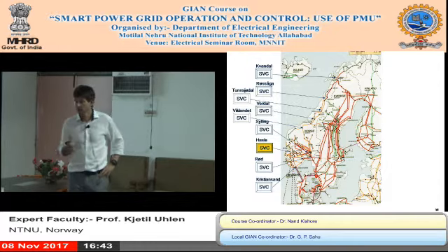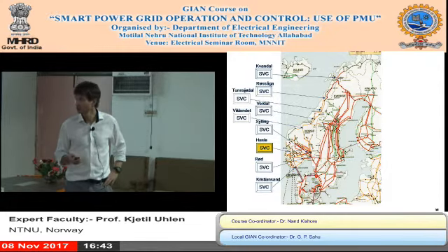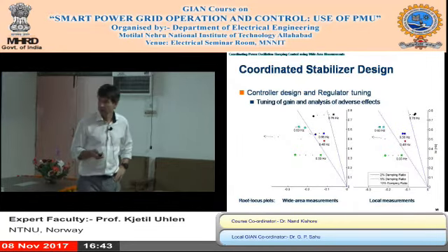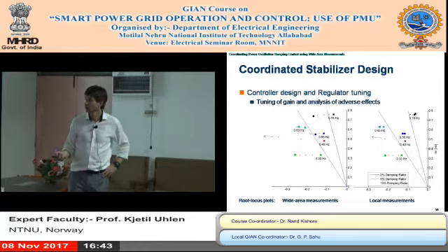We started out with analysis, both small signal analysis and transient analysis, and we observed that with our controller we were able to damp both these critical modes. The 0.3 Hertz mode initially here was shifted very easily to the left. 0.3 Hertz mode also.